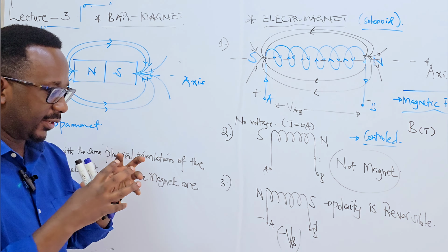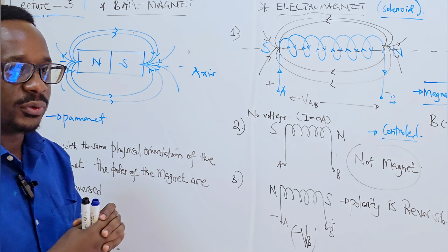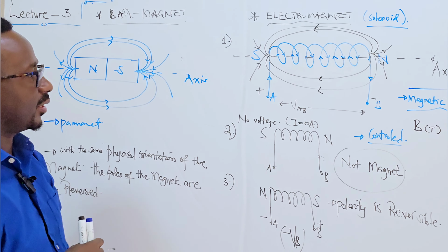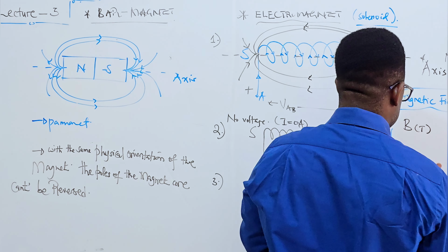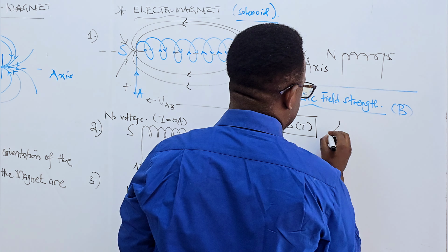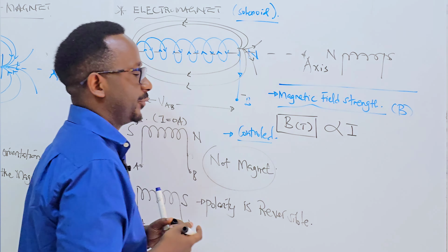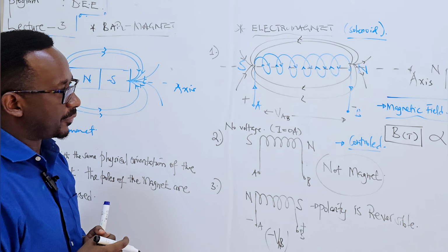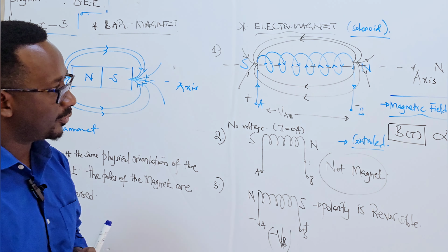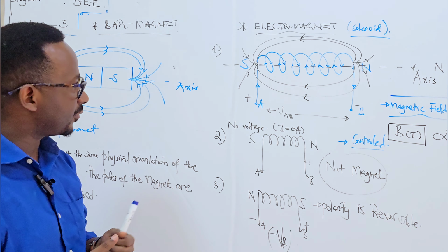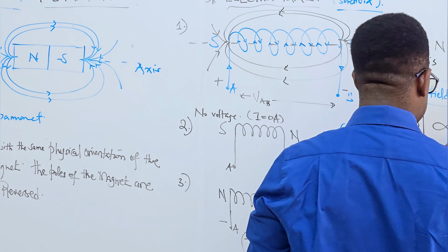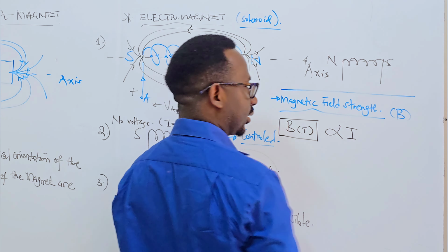So guys, now we are getting into the technical stuff that affects DC machines and batteries. The magnetic field strength, we've realized, is proportional to the current flowing through the coil. So if we find ways of manipulating the current through that coil, we can manipulate the strength of that magnet, right? Very, very important. The strength of the magnet can be easily controlled by controlling the current.